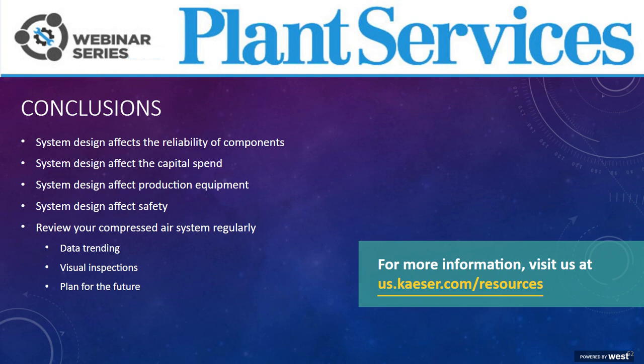Typically, if you have more than one compressor and those machines are loaded, you want to take a look at what that pressure drop is in your air station. So if you're trying to avoid it, let's say you turn one compressor off and widen your pressure band, you can figure out if only one compressor is needed to operate that system. So, that's one thing I would definitely look at.